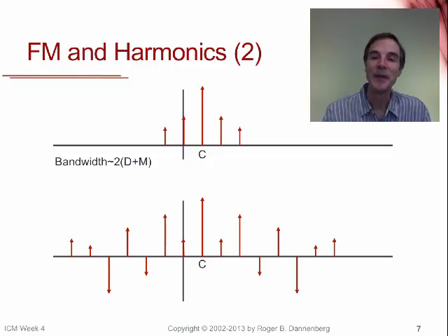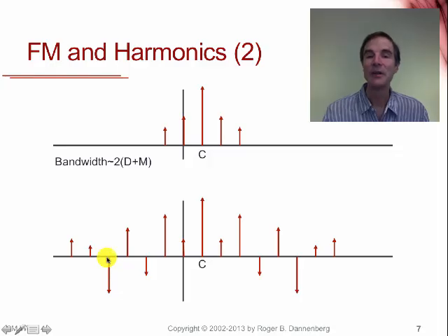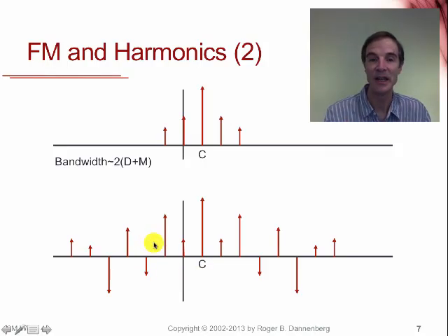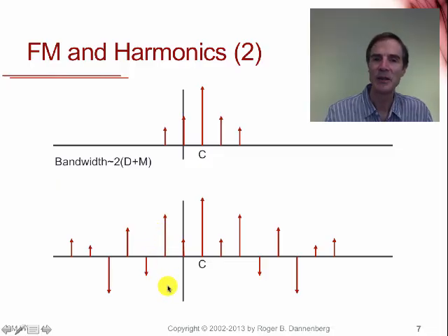But getting back to negative frequencies, suppose we increase the depth of modulation a lot so that we get lots of sidebands. So now we have all these sidebands. Some of them are shown at different amplitudes, including negative amplitudes, to reflect the fact that they are described by these Bessel functions, and in fact, they do have different phases, or positive and negative. And so what does this mean in terms of the signal that we hear?